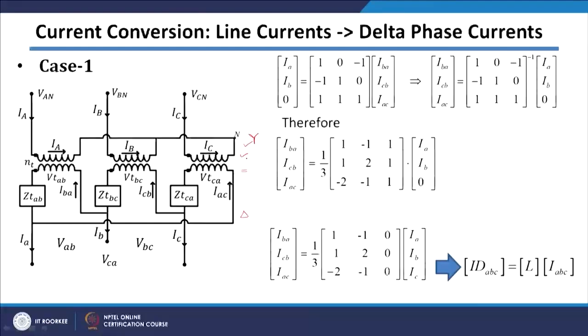there should be balancing current from the secondary winding. So, whenever 0 sequence currents are flowing in one winding, there should be 0 sequence current flowing in another winding. So, since 0 sequence currents are not there in Y here, there will not be 0 sequence current in delta. So, if the 0 sequence current path is not available, we can easily write 3 equations here.